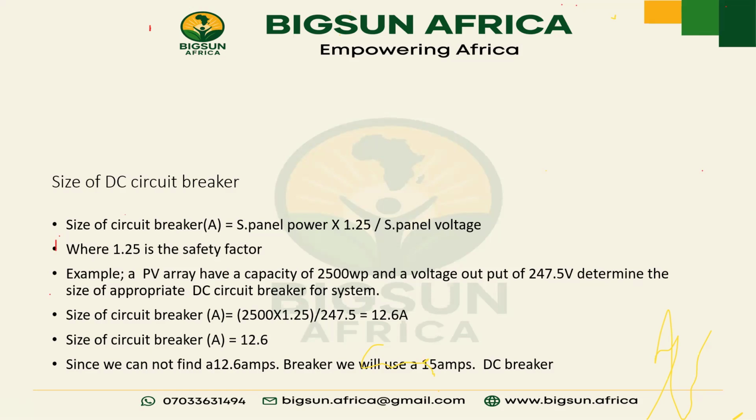When you connect the panels in series, the overall voltage you got is what you're going to use for your calculation. Because by system voltage, I think you mean the voltage of the inverter. That's why I'm asking. No, not the system voltage. The overall, the total output voltage. Okay, so that I can verify.